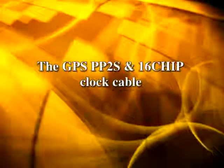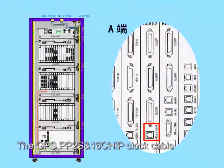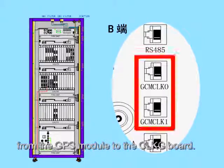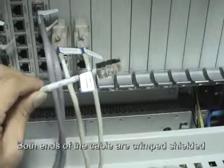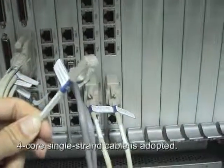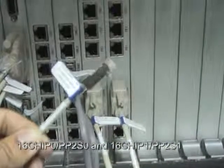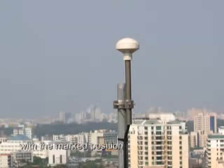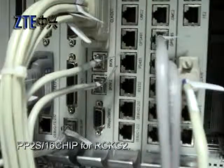The GPS PP2S and 16-chip clock cable. The GPS PP2S and 16-chip clock cable outputs the PP2S and 16-chip clock signals from the GPS module to the CLKG board. Both ends of the cable are crimped shielded plugs for 8P8C straight cables. Round 4-core single-strand cables are adopted. End A is connected to the positions 16-chip 0, PP2S0 and 16-chip 1, PP2S1 for the GPS module. End B is connected with the marked positions PP2S 16-chip for RCKG2.